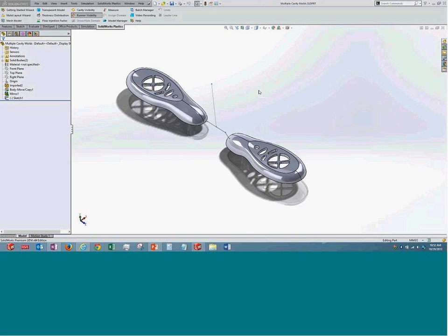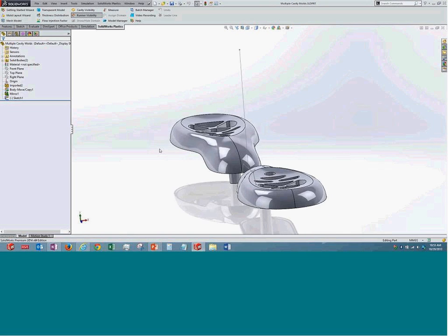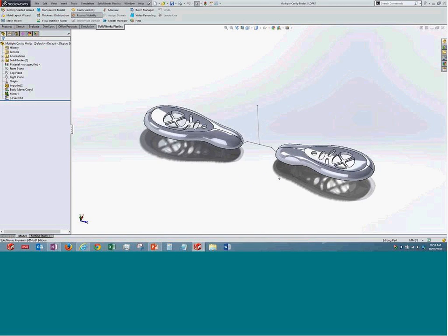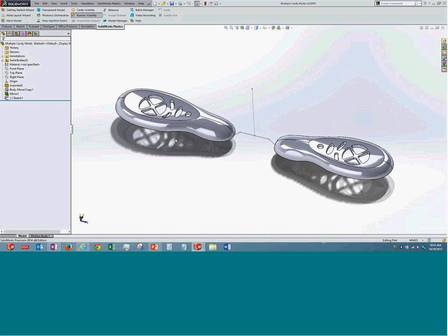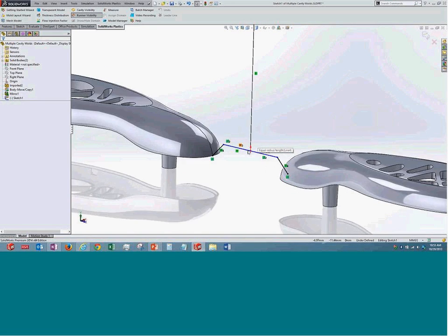To that, I'm going to show you here. Typically plastic parts use a huge set of parts which are injected at the same time. In this simple example, this particular cavity has been copied and two entities are present. A sketch is created. So in SolidWorks, we need to create a sketch which is going to represent that particular runner system, which will fill these two cavities. So just create this 3D sketch, which is going to be used for filling the part. This is an extra step which is required in SolidWorks.